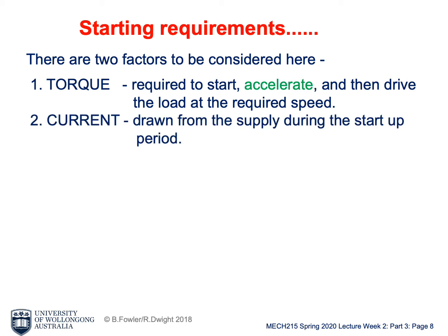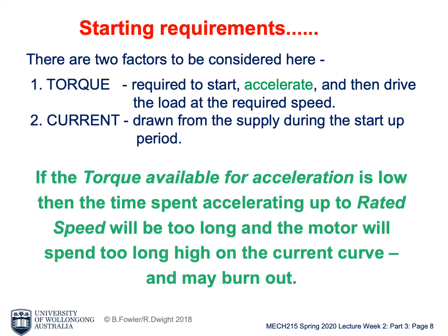Secondly, the time during startup should be short enough, or the current going through during startup needs to be small enough. Otherwise, you might end up having a very large current going through your motor for an extended period of time, and then the motor will be damaged, or your system power supply might be damaged. Your other components on the power supply might be impacted.